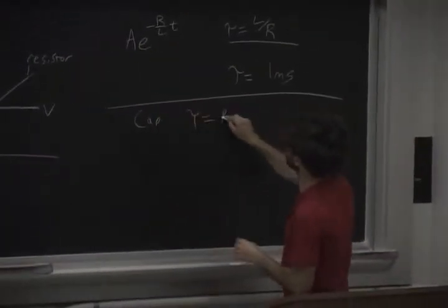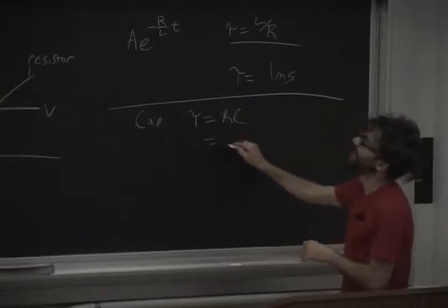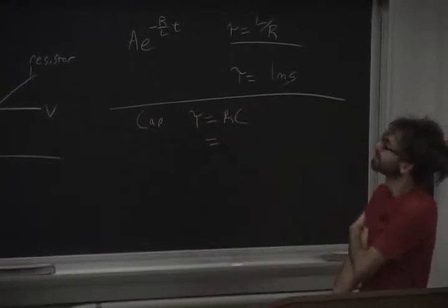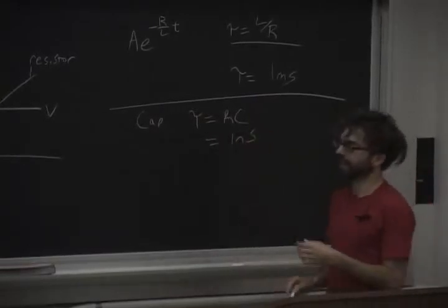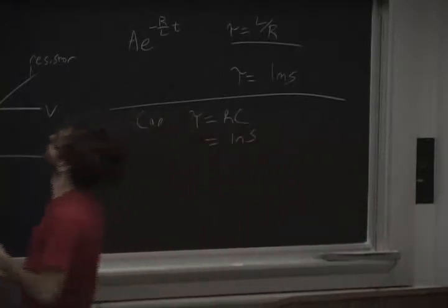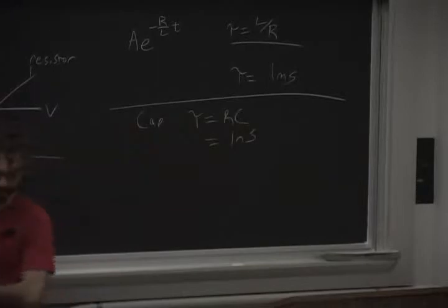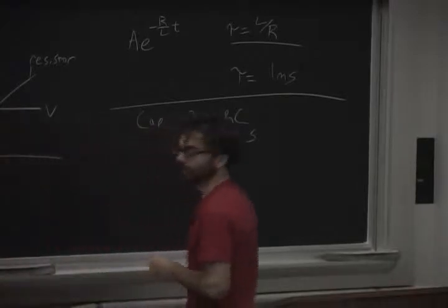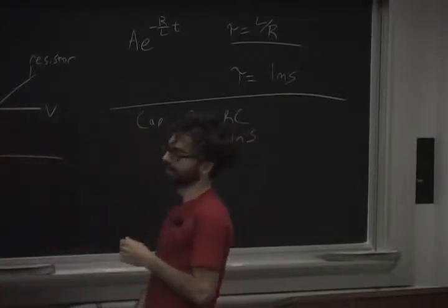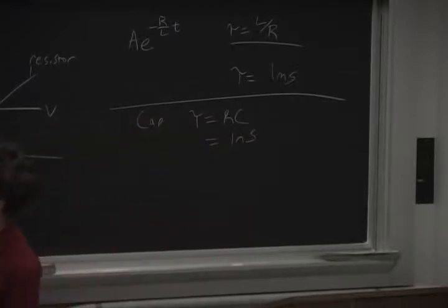What's RC in this case? 1 nanosecond. Are you that fast? Not. So what are you going to see on here if you measure the IV characteristic of a capacitor? It'll be this one. Horizontal line, I equals 0, because in the time it takes you to measure, the current that will appear briefly goes away.